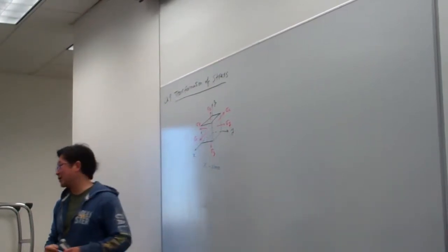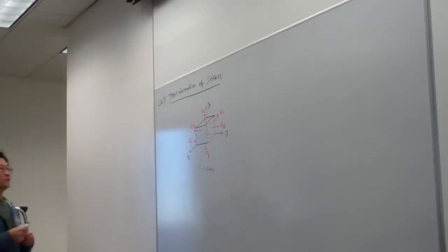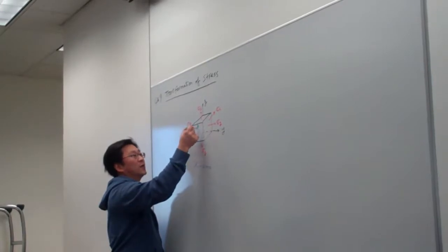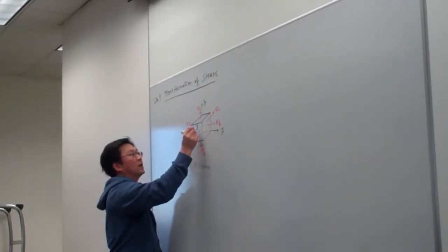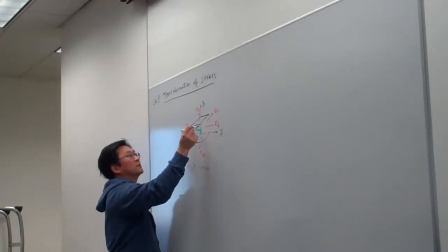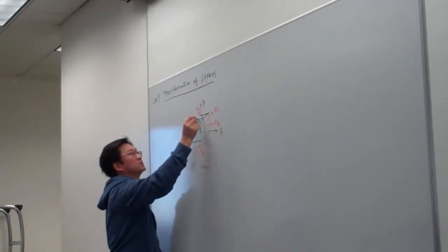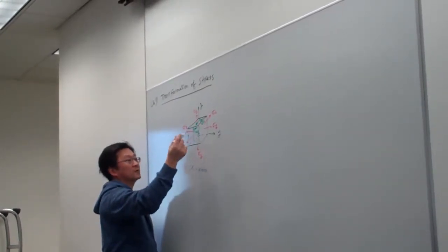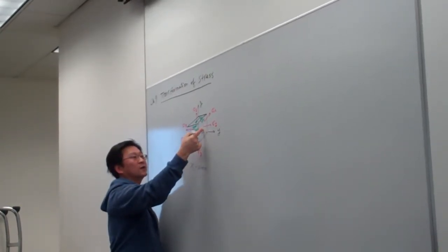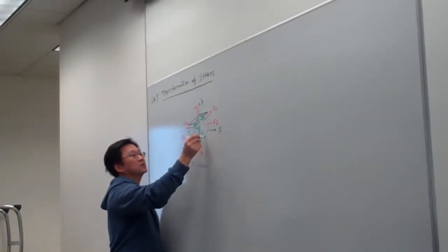So the shear stress on each plane would have this direction, tau xy on the plane, and pointing to z direction, this is tau xz. And this one is in the z plane, pointing to x direction, so this is tau zx, and so on. So let me make one more. For example, on the x plane, pointing to y direction, this is tau xy.